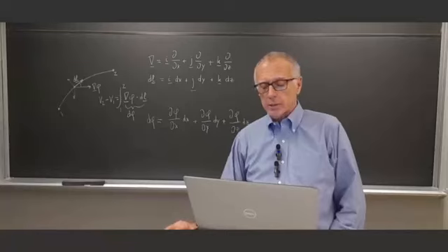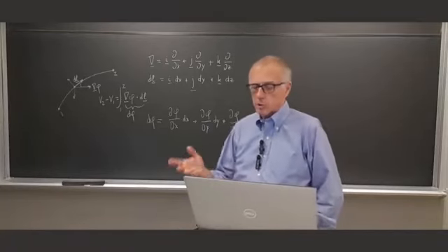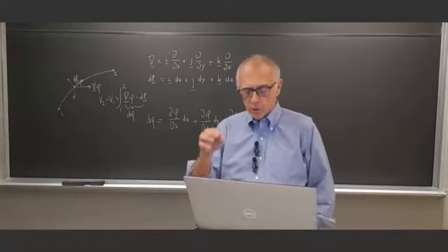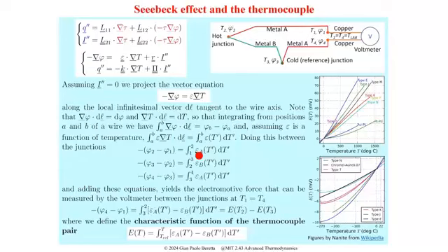You could, but that would be an approximation, unless you use the proper average in that temperature range, because Seebeck coefficients are functions of temperature. So let's keep them inside the integrals this way.